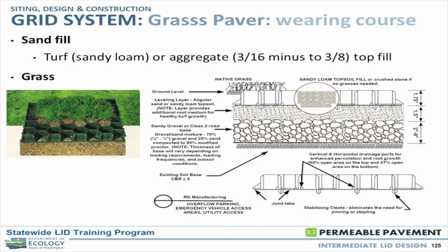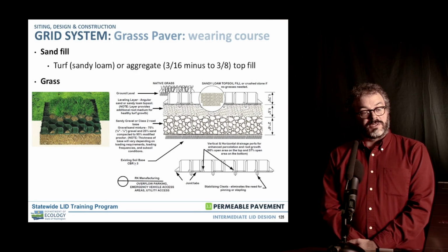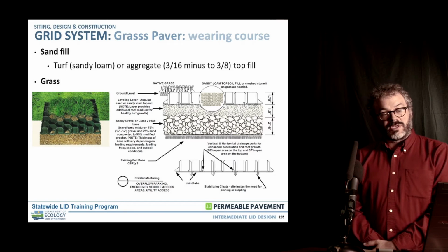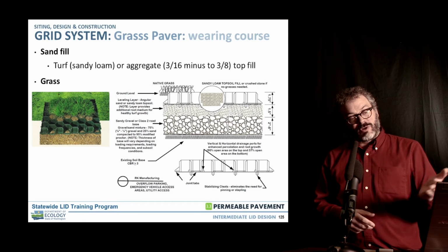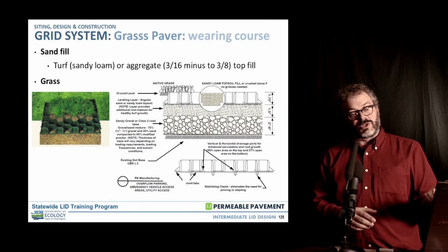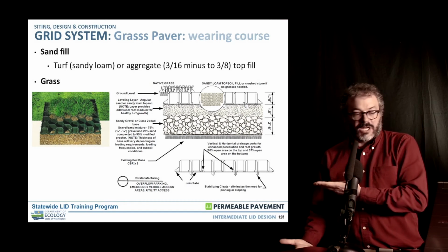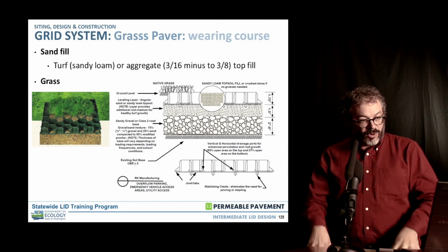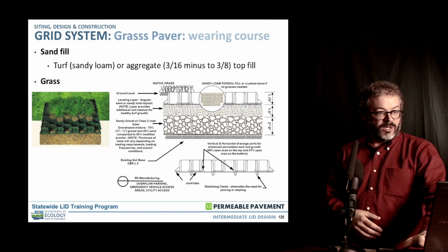So this is the example. The drawing there is showing a different product, the grassy pavers product, but it's showing how you've got a kind of finer grained soil. In the manufacturer's image here, I'm not so sure how that really sandy material is going to sit on top of that open graded material, but in the cases where I have used this, I've not had a reservoir course like this manufacturer is showing, but instead have had more of a coarse sand section that allows the grass roots to grow down into that section, but also maintain some good structural capacity and infiltration capacity.